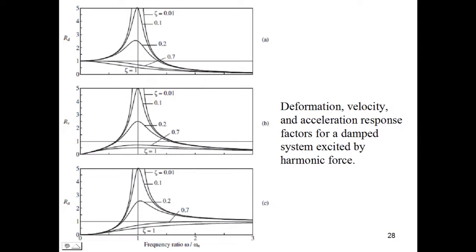The following figure shows the deformation, velocity, and acceleration response factors for a damped system excited by harmonic force. The deformation response factor Rd is unity at omega over omega n equals 0, peaks at omega over omega n less than 1, and approaches 0 as omega over omega n approaches infinity.